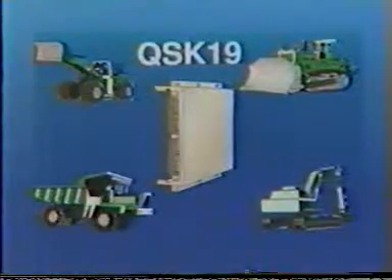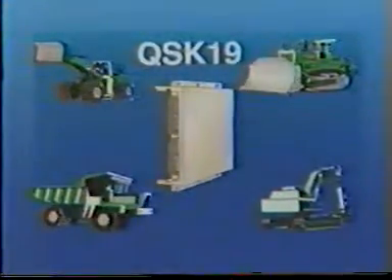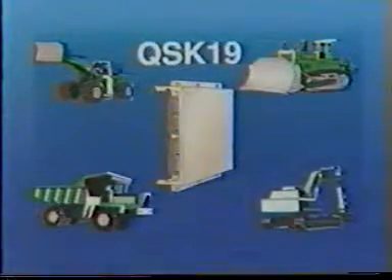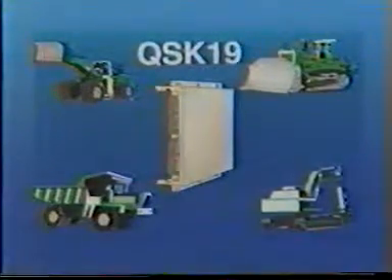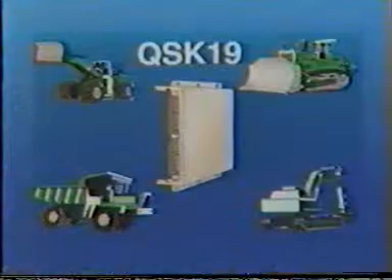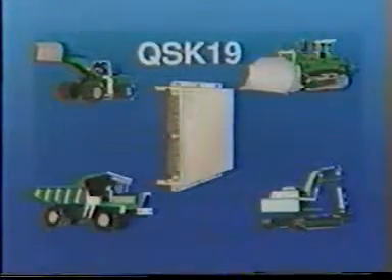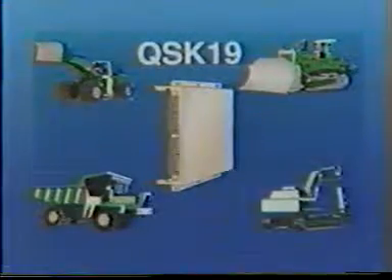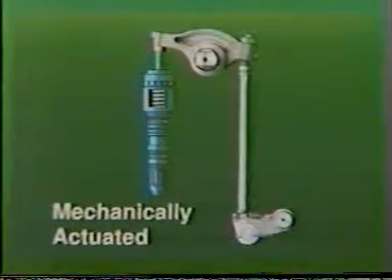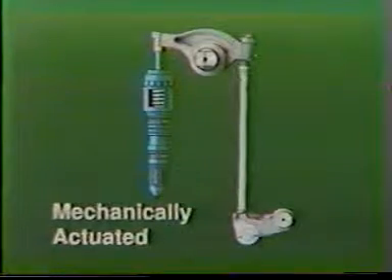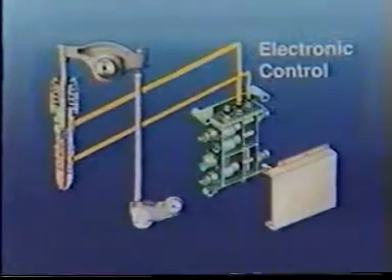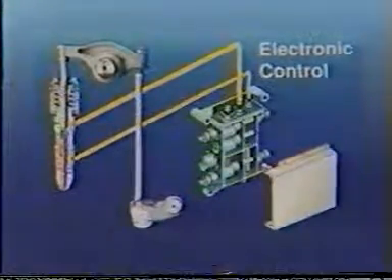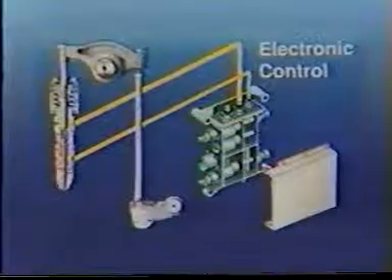Currently, the QSK-19 fuel system is being used on the new Quantum System K19 or QSK-19 engine, which is intended for heavy-duty industrial applications. In the future, Cummins will bring the efficiency of the QSK-19 fuel system to other engine platforms as well. The QSK-19 fuel system features a mechanically actuated open nozzle type injector. And, using the latest generation of Cummins electronic controls, provides precise fuel management and infinitely variable injection timing.